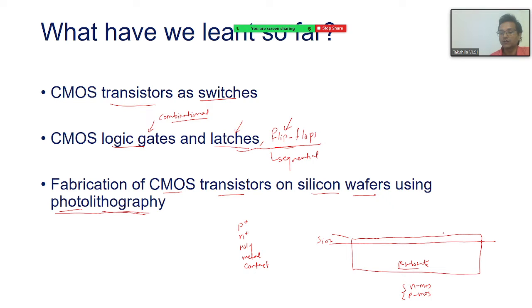So I know what I will do. This is the SiO2, and then I will deposit one more material that I call photoresist. This is photoresist. It's a thin organic polymer. If you recall the concept, I said this is the thin organic polymer that helps us fabricate the particular layer or particular division in a specific area of this wafer.